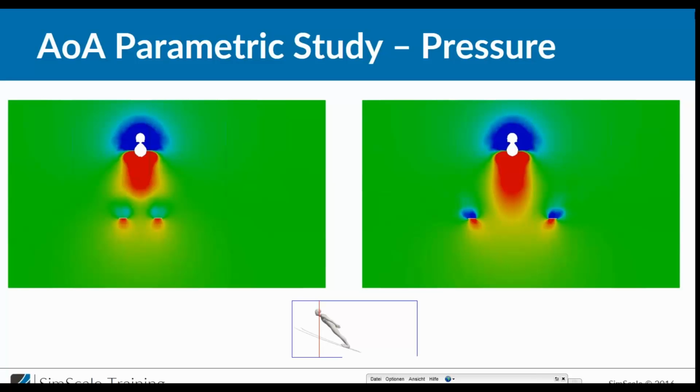Yes, exactly. I think that's right. Absolutely, this difference of pressure on the skis will create more lift, and actually I'm going to explain why. We can see clearly that for the parallel position we don't have a high difference of pressure, but with the V angle we have a significant difference of pressure. For the parallel one, we have this stagnation pressure in front of the athlete, and this high pressure will affect the low pressure on top of the skis.